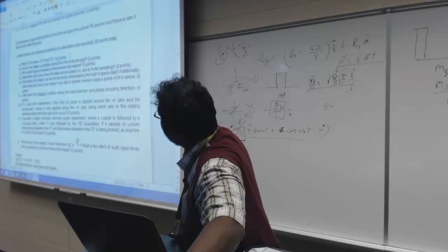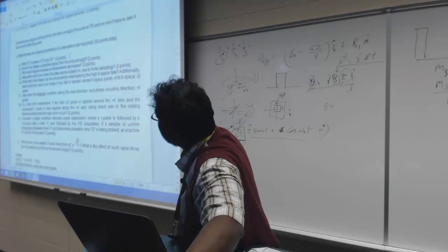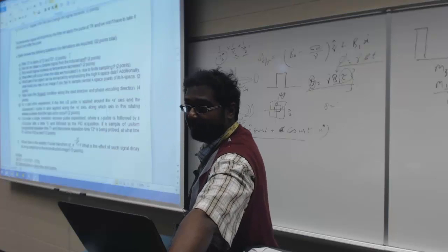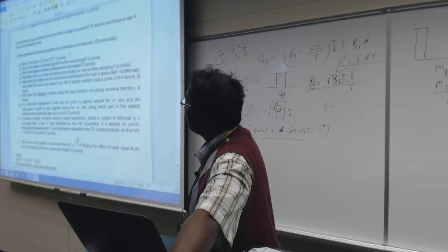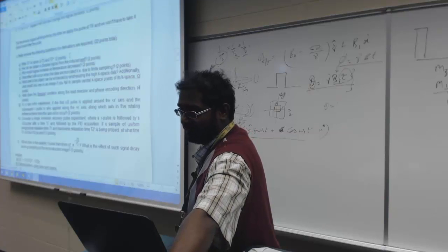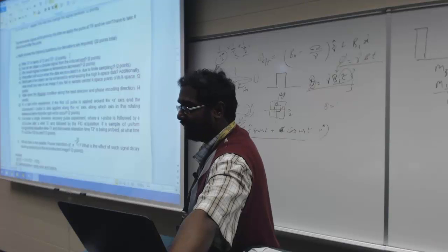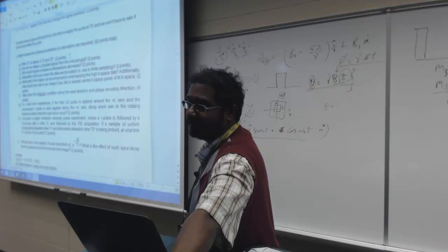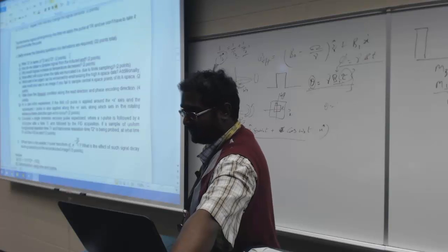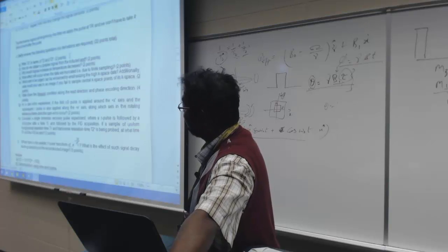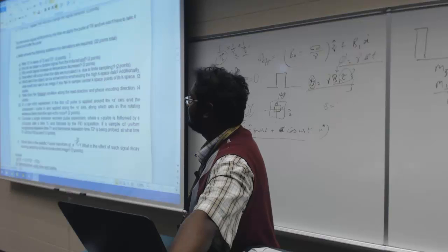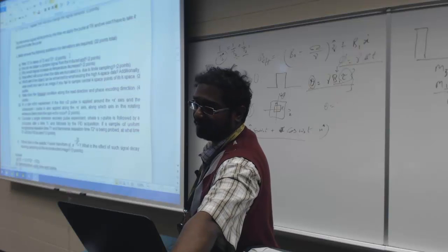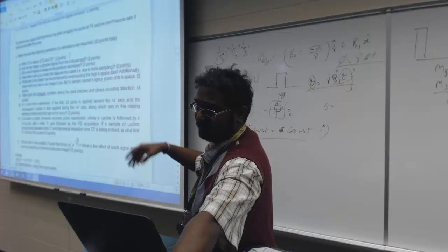Okay, data truncation. So part D, does everybody know the answer to that now? Everybody understands that? So there are two effects, right? One is the finite sampling effect, and the other one is the data truncation effect. Data truncation causes Gibbs ringing. Finite sampling is the one that is leading to your aliasing problem, right?